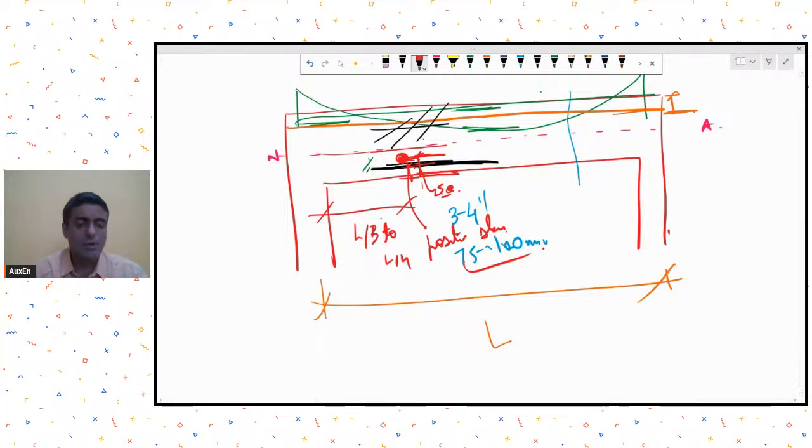Now, if I do this, and if this sleeve was planned after the beam has been constructed, I cannot do much when it comes to strengthening this. Maybe I can fit in a GI pipe inside. Why a GI pipe? Because it will add some strength to this weak zone that I have created. Maybe I can do that. Most of the people don't do it.